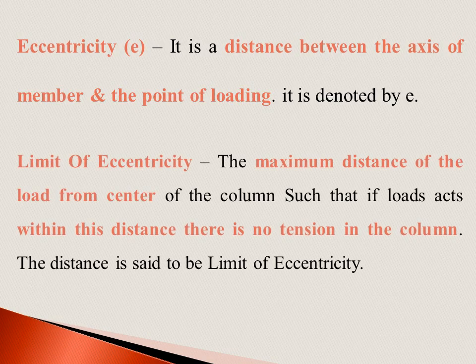Limit of eccentricity: the maximum distance of the load from the center of the column such that if load acts within this distance there is no tension in the column. The distance is said to be limit of eccentricity.